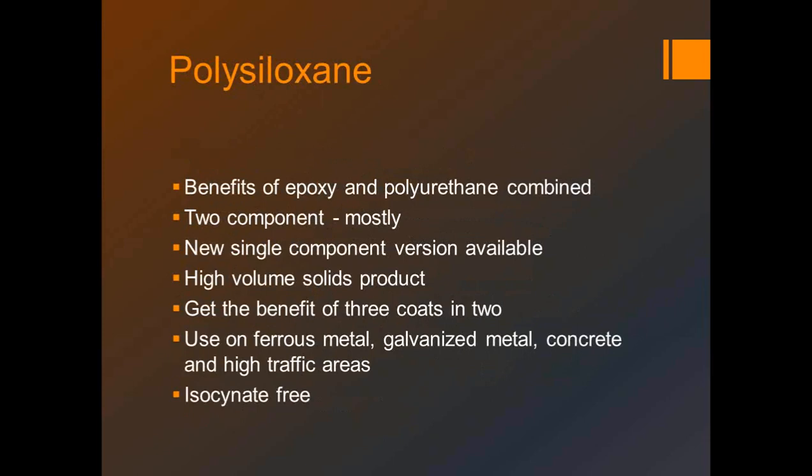Great. So here's a question from Dwayne F. asking, are polyurethane and polysiloxane good finishes for cement board where we need good color retention? Well, on cement board and things of that nature, I would personally go with 100% acrylic paints. Lewis mentioned something about hardness of finish, and polyurethanes and polysiloxanes are very hard finishes. With cement board, we need some flexibility, because normally those things are put on surfaces between studs and so on, so you do get some flex with that.